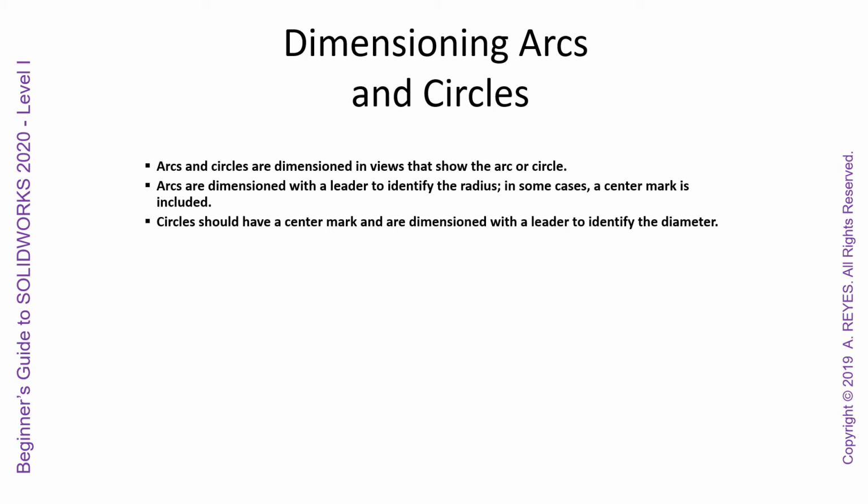So again, with the new geometric dimensioning and tolerancing, everything is going to be measured to the center mark. We can go into a whole lot of reasons why, but we can do a whole semester on just GD&T. But just know that they'll have a center mark there, and that's typically where any type of circular feature is going to be measured to.